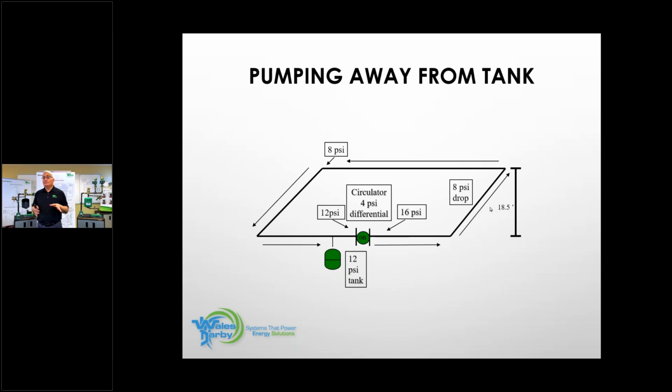So if I don't have room, let's take advantage of other things that we've talked about. If I don't have room and I can't move it, change that air scoop to a 4900. All right. No piping minimums needed. This will get the air out of your system too, and you can fix that problem.